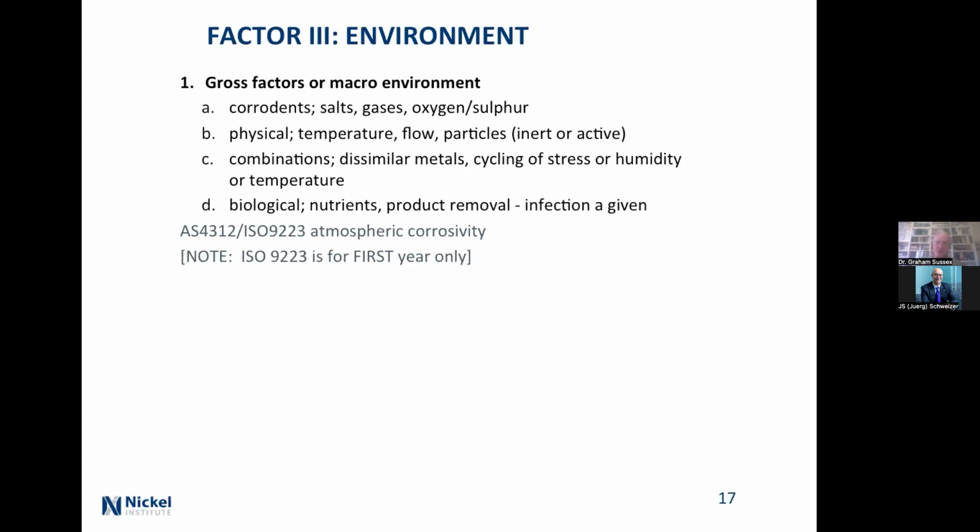Is something going to be suffering from fatigue? Because the austenitics don't have a clearly defined fatigue limit. They basically quote for 10 to the 8th cycles or something like that. What's the humidity? Is it going to be condensing? How hot's it going to get with the sun shining on it?